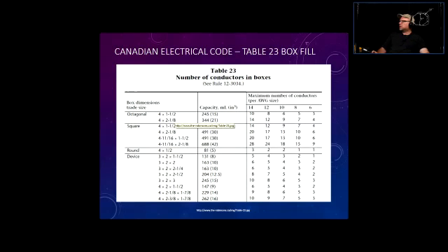And here we have different sizes of wires: gauge 14, gauge 12, 10, 8, and 6. We know that gauge 14 is the thinnest. As we reduce the number that represents the gauge, the wire gets thicker. So this is the thinnest, this is the thickest wire. In that box we could fit 10 conductors that are 14 gauge.